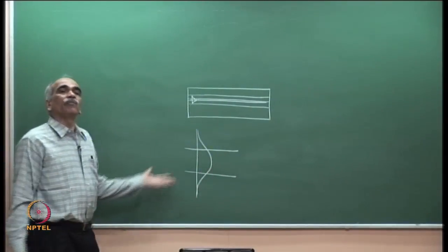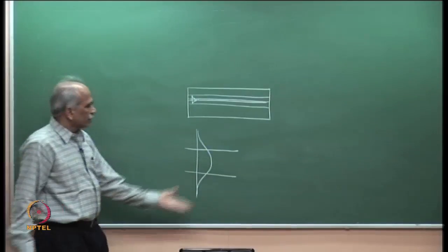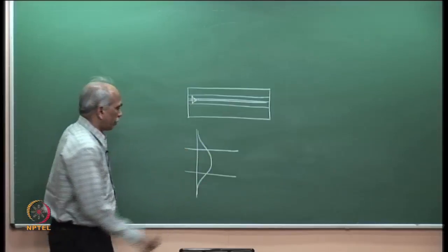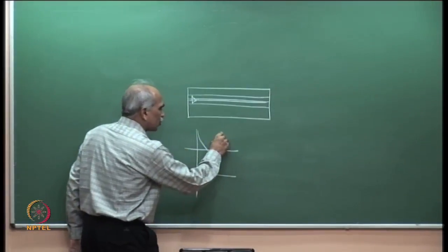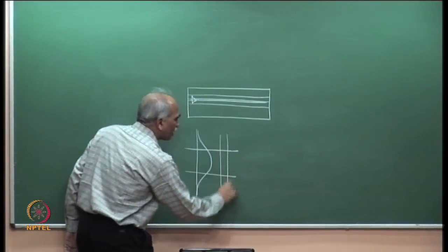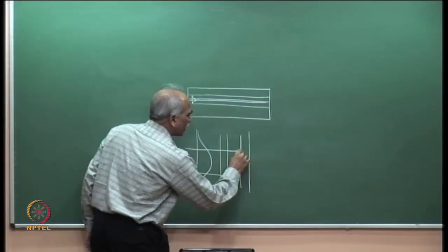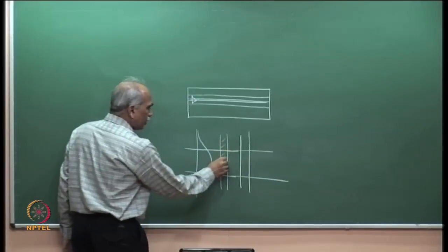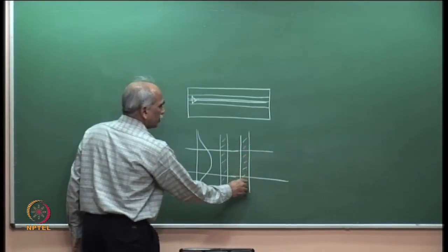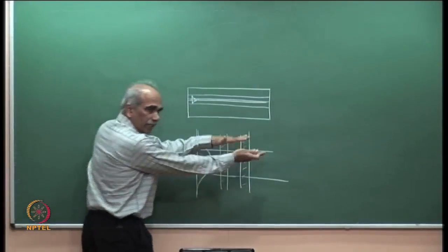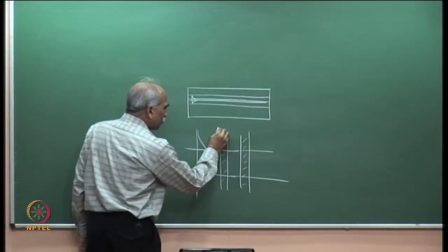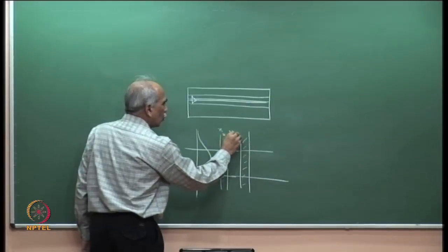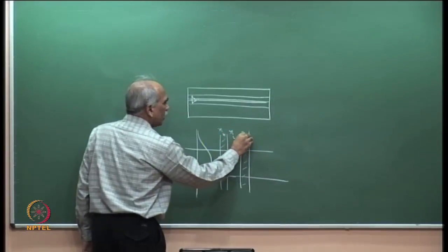Many of you have studied fiber Bragg gratings, where there is a grating in the core of the fiber. So, if you have a periodic structure, let us say there is a periodic refractive index variation in this direction. There is a guided mode which is propagating, but it encounters a periodic refractive index variation. So, n high, n low, a modulated n high, n low.